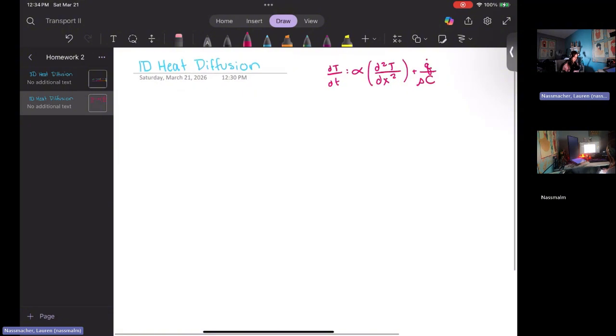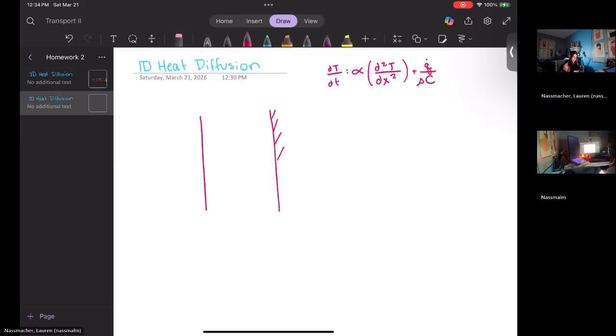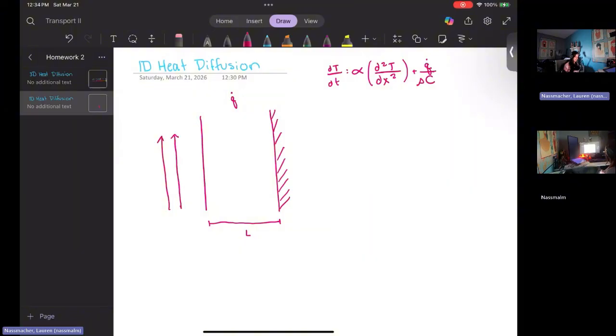So let's say that we have a slab, and on one side of the slab, there's insulation. The slab is of length L, and there's obviously heat flow through it, and there's air traveling up on one side. That air we'll say is 20 degrees on the outside, and the slab is 80 degrees Celsius. Our heat is flowing out of this volume.